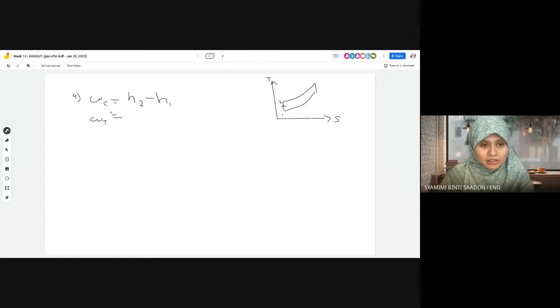So the energy balance becomes only work and enthalpy. And the turbine work, 3 to 4. We start with H3 because H3 has the higher temperature, and we want a positive value. So H2 minus H1 for the compressor, and H3 minus H4 for the turbine.